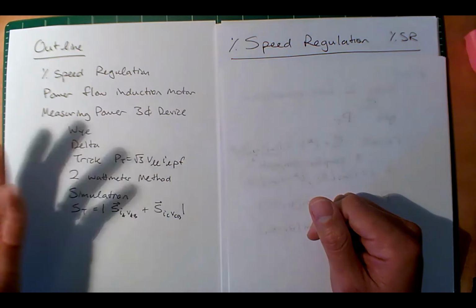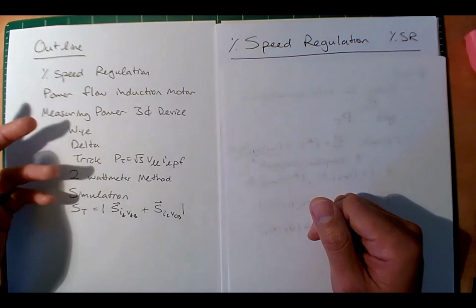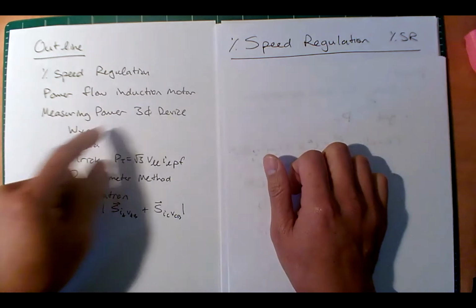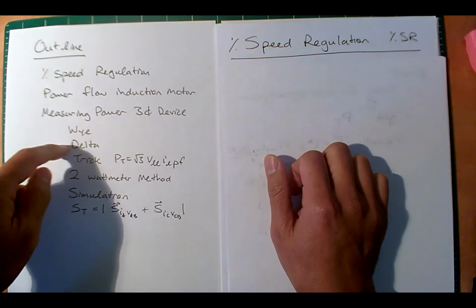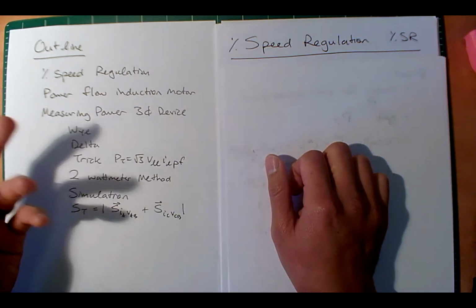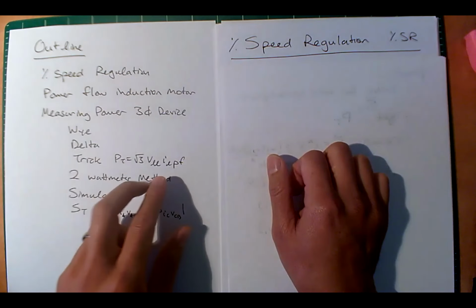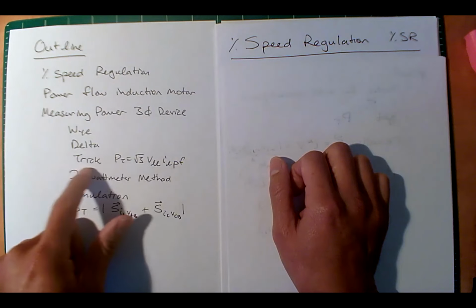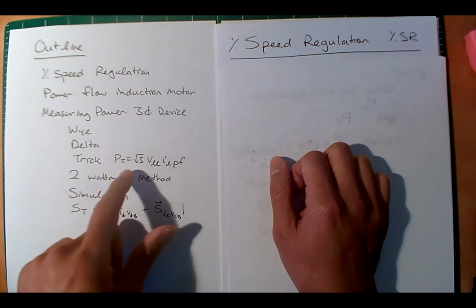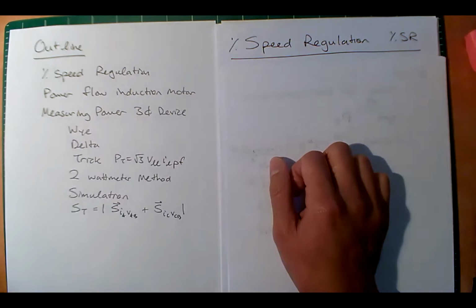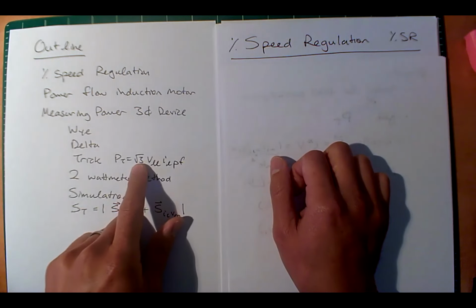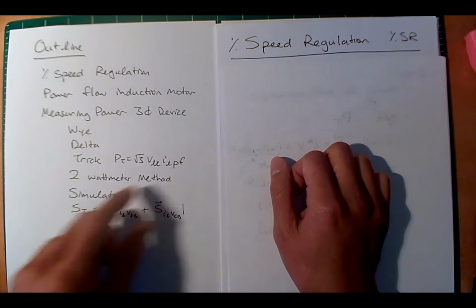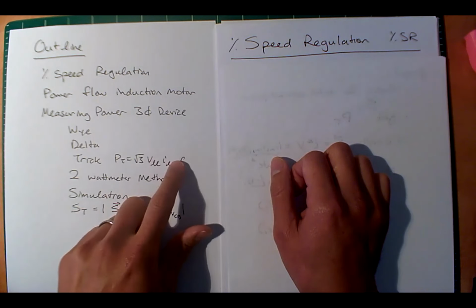And what do we have here? Well, we know we have Y and delta. And so we'll look at a bulletproof way to measure three-phase power in Y and delta configuration. But then with some issues with getting the currents and voltages, it might be more convenient to get the line current and line-to-line voltages. So this is kind of a trick where you can measure total power for a three-phase device where you have a √3 here and a power factor. We'll talk about this. Now this has some assumptions of balance and knowing this power factor.